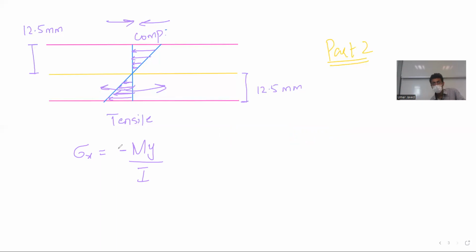Similarly, you have a y equals mx plus c kind of equation. The more you go away from the neutral fiber, the more linear the increase in the stresses. So this bent line that I'm making is a mathematical line, because it shows the magnitude of stresses. Okay, everyone, just one last question: what is the stress here? Zero. What is the stress here? Maximum. So y equals mx plus c, linear variation.